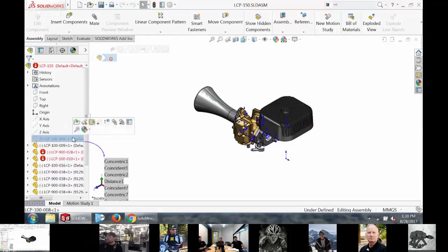How that happened is there's two ways that a part assembly can open up with parts suppressed. One way is if it can't find the file name, it's going to find it as suppressed. The other way is if the internal IDs do not match. This one was an internal ID match issue.